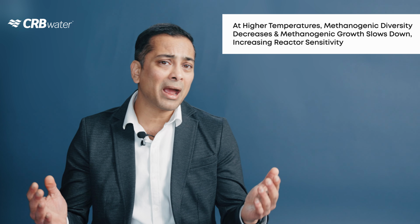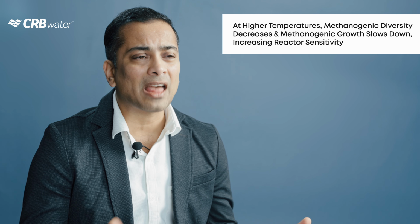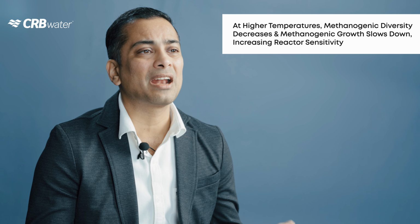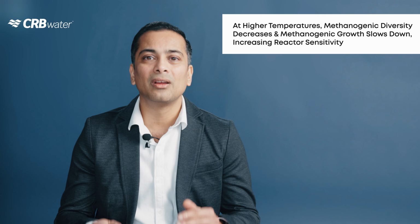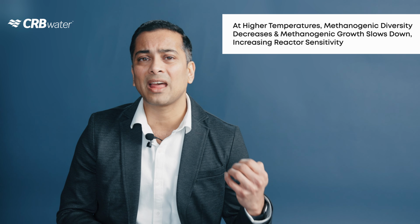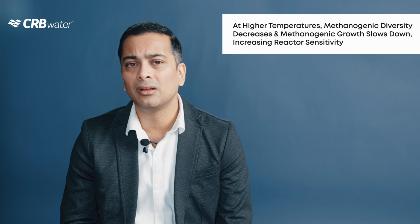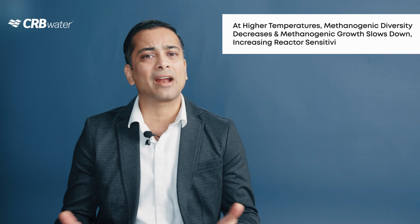Higher temperatures impact the growth of methanogens, and some studies have shown that thermophilic methanogens may have 50% biomass yield compared to mesophilic methanogens. Moreover, only a few methanogenic species can function at higher temperatures, reducing the methanogenic diversity in these reactors. Lower methanogenic yield and lower diversity increases the chances of reactor upsets. Moreover, the adaptation of thermophilic methanogenic cultures to a variety of substrates poses a significant challenge due to their slow growth rate.